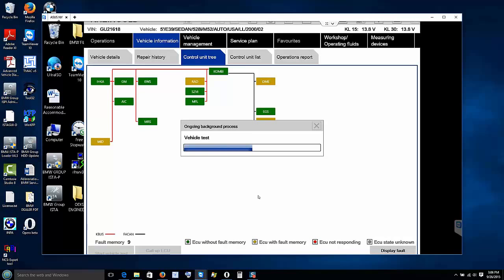Yeah. Like the DSC still have code in it, man. Maybe. Well, on there, we did have 2 codes for it, you know. But we can look on them one day, you know what I mean? And see if it's causing the steering angle sensor not to calibrate properly. But the calibration is something simple, you know. So maybe we have to look at other fault codes that have to do with it in the fault code entries and see what we can do with that. We'll calculate a test plan for that one too as well, you know what I mean? Yeah. Mm-hmm.